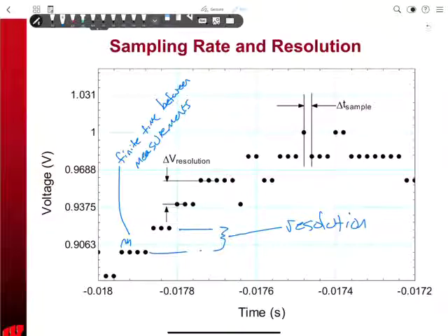Right? Just like if I pulled a sock out of my bottom drawer, I know it's good from 0 to 10 degrees, right? And I don't know any more than that. All I know is it's good from 0 to 10. So on this particular oscilloscope, I only know that those dots there mean it's somewhere in that range. That's the best my analog to digital converter can do. That's the best my resolution has.